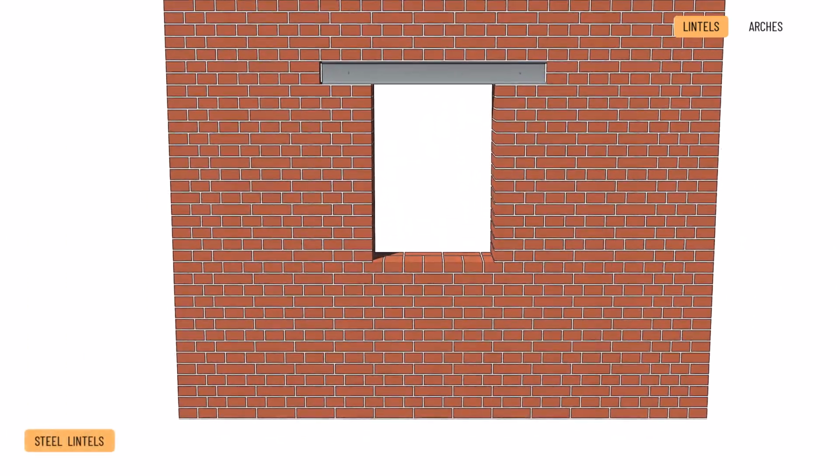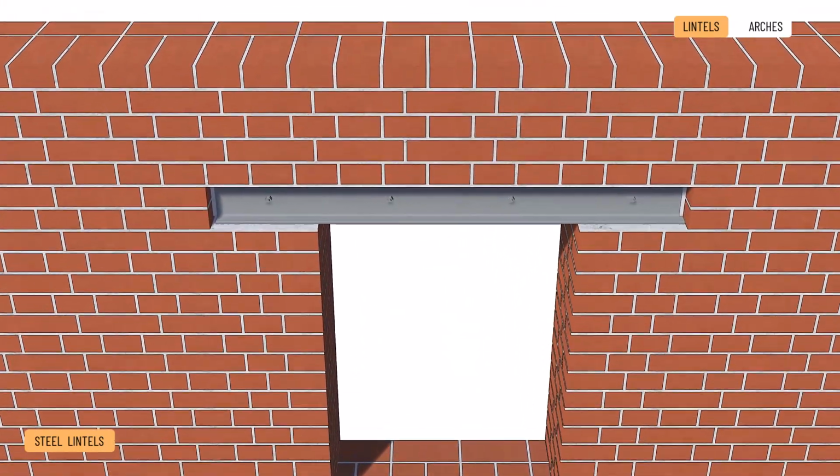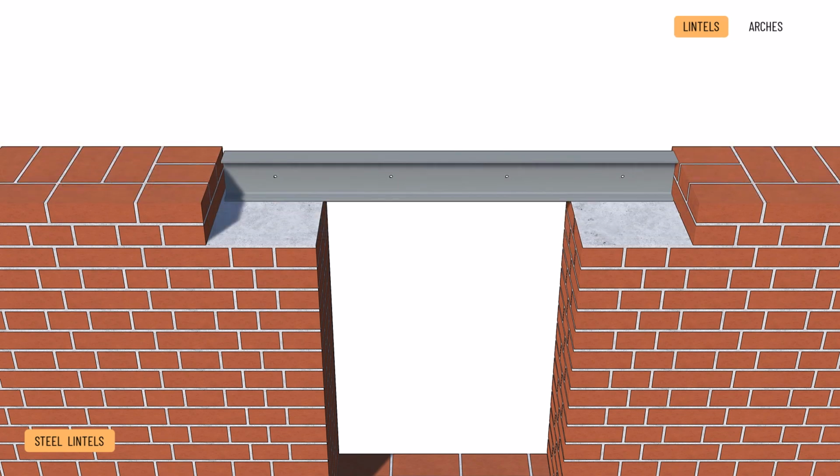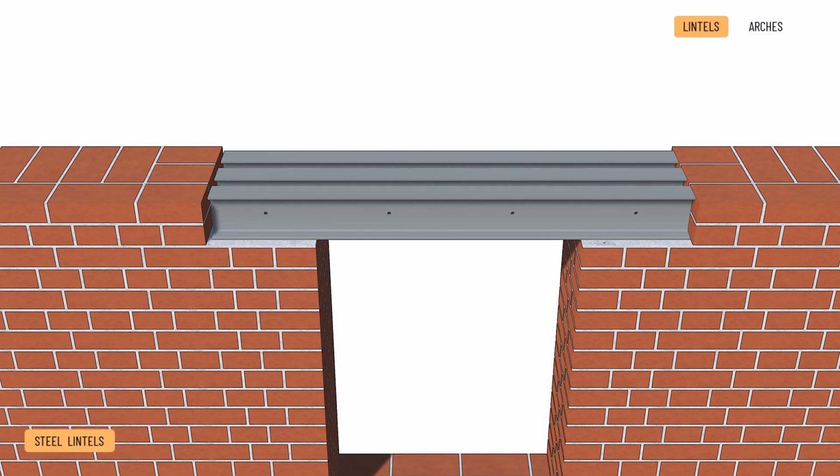Steel lintels. In the 19th century, additional materials appeared that performed the function of lintels economically. One is the steel beam, mainly built of I or U-section beams, or from their alignment. The beams must be bolted together at 1 meter intervals in the aligned arrangement. The required bearing width for steel beams is 1.5 to 2 times the beam height, typically placed in traditional small element brickwork. Under the beams, the bricks are placed in cement mortar or cast in concrete for structural reinforcement.